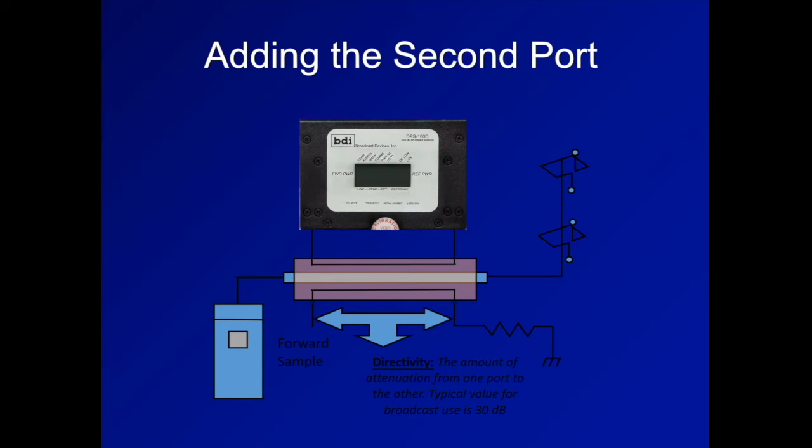A good spec for AM noise is 50 dB or better. If you can get 50 dB of synchronous AM noise out of a system, you've done pretty well. Now, let's take the example of a directional coupler with a directivity of 20 dB.